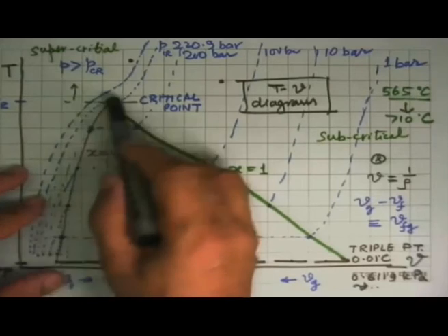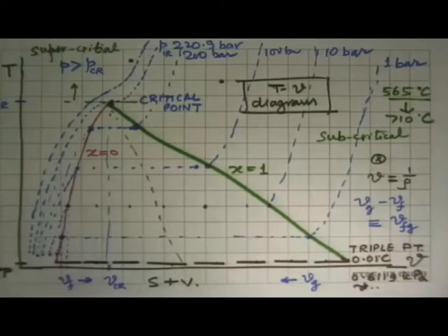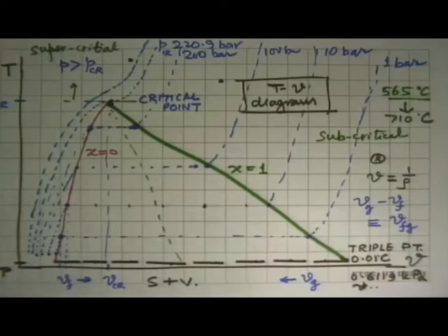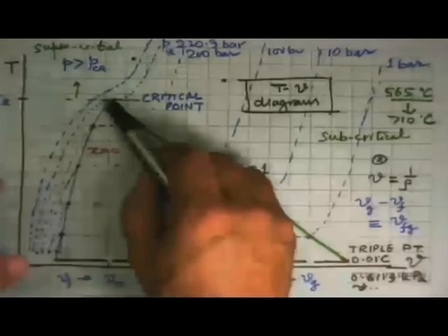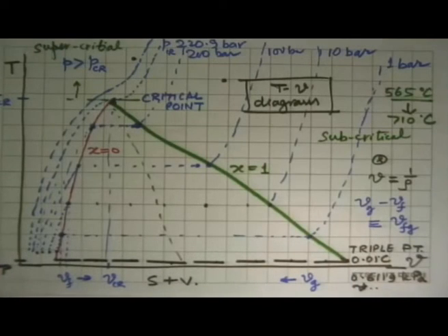It continuously shows a behavior of one type only, where the intermolecular spacing is now fairly tight and very close, and it doesn't show that it has any ability to become a vapor by getting the molecules very far apart. So that's why this happens here. And of course, if pressures are more than the critical point pressure, there is absolutely no hope, because now you have compressed it so much, molecules are so close to one another, they have no chance to get away from each other.